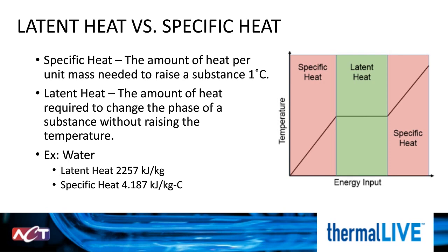Water is just this awesome thermal fluid due to those hydrogen bonds which occur between molecules. The hydrogen bonding in that liquid phase leads to a high latent heat value of 2,257 kilojoules per kilogram. Its specific heat is only 4.187 kilojoules per kilogram degrees Celsius. This means that water will absorb 540% more thermal energy per unit mass as it's converting phase compared to it raising in temperature.